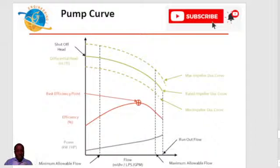So when the flow is 0, what do you think happens? The differential head generated by a particular centrifugal pump is going to be maximum at zero flow. At zero flow with maximum head, that point is called the shut-off point, referred to as the shut-off head.